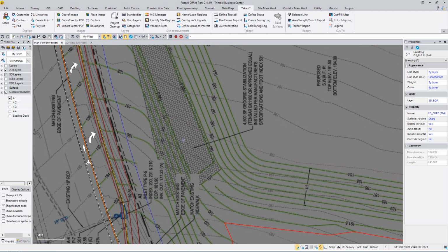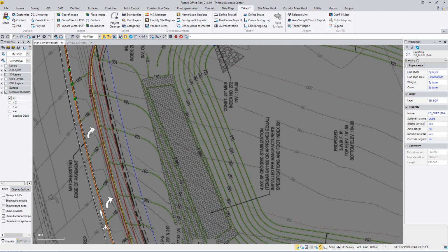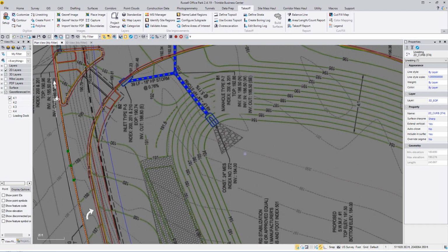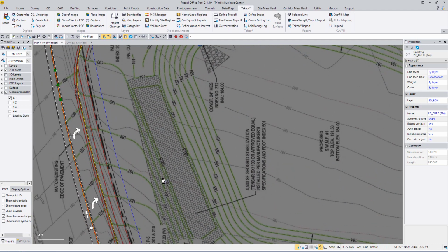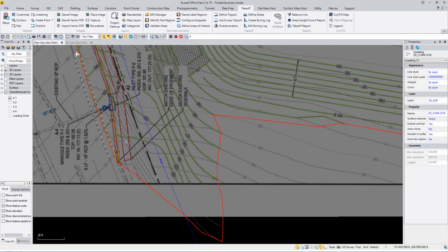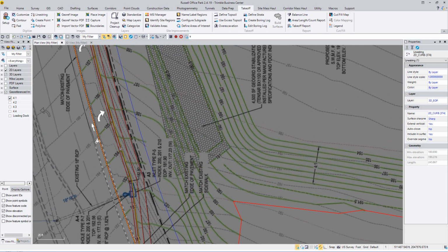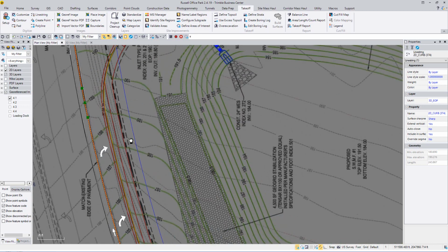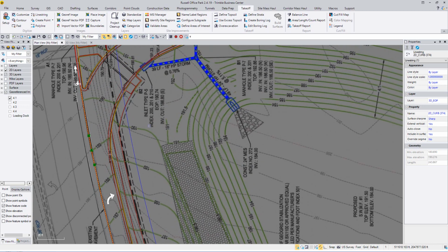we've got to make sure that we are in good shape to pick up this riprap, to channel water down here and get into this pretty big retention, because if we don't, there's going to be some problems with either pooling, or it's going to try to take water and put it back onto the street if this changes enough. So we've got a sidewalk to match here. All these things come into play, and we're going to adjust the project, make it work with those saw cut lines that were now measured, and then propose those changes.